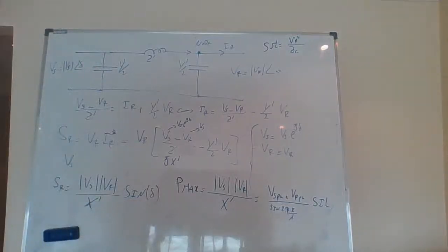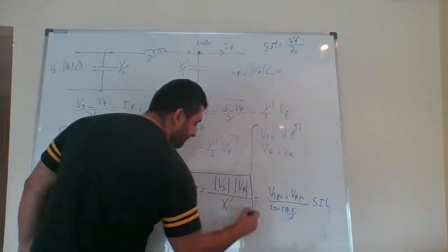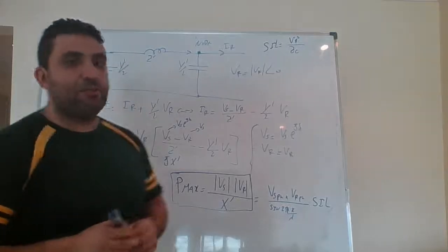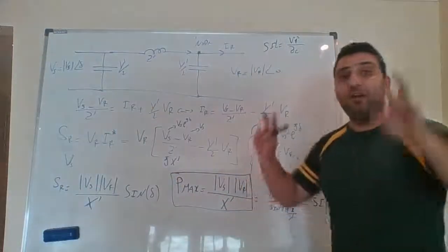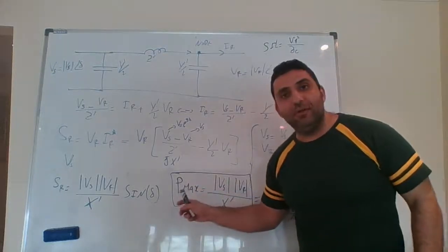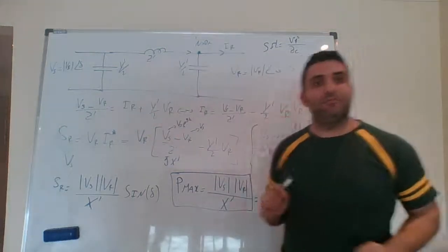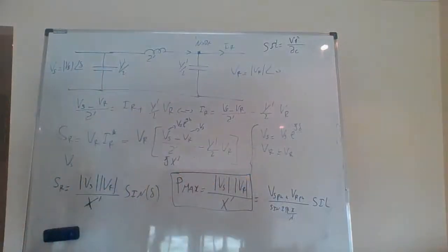From the previous one, the maximum power, when we did this, remember the power under the surge impedance loading? Now, this Pmax, see this Pmax in here? It represents the maximum possible power that the transmission line can transfer theoretically. And if the power exceeds this value, you will lose the synchronization between the sending and the receiving voltage. Is that clear? That's the importance of a transmission line system.